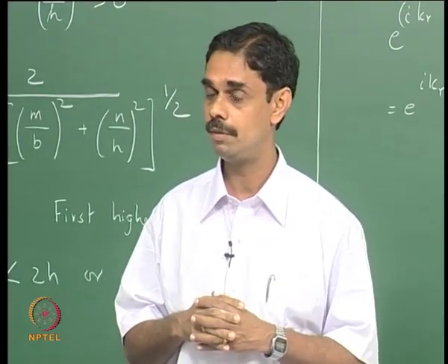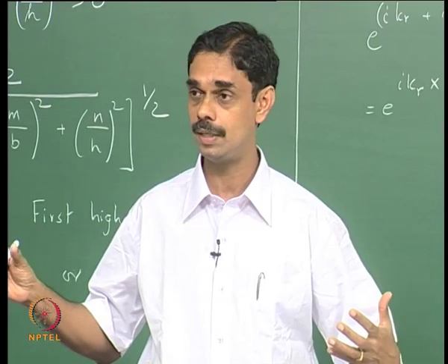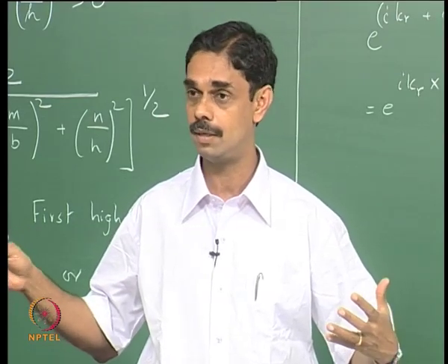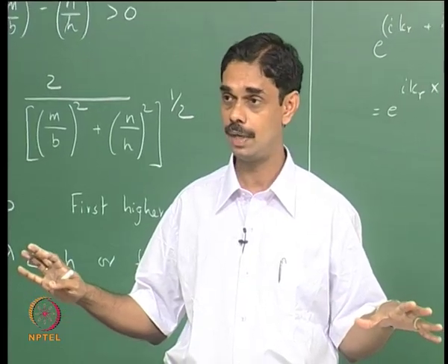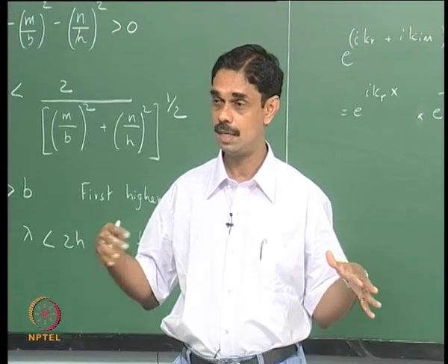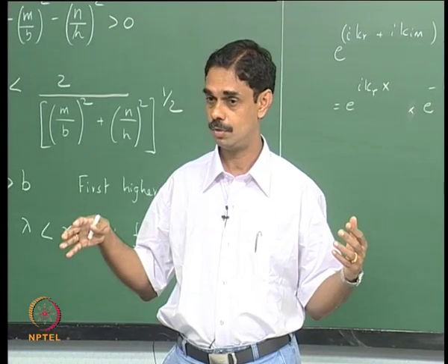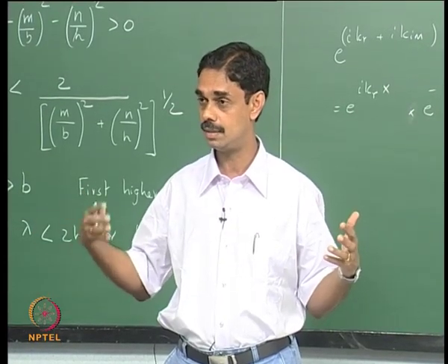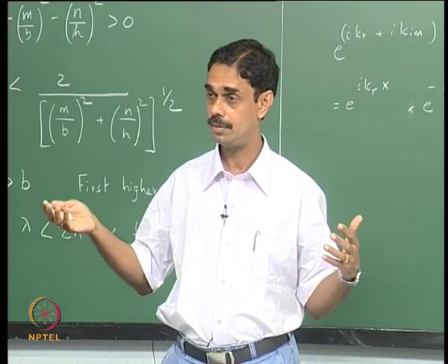When we looked at the attenuation of sound in a duct, we said that there is a loudspeaker producing sound, and the experiment is running in a kind of steady state. So we have a real omega and a complex wave number, and the question was whether omega over c is k, omega is real, so c has to turn out to be complex for k to be complex.